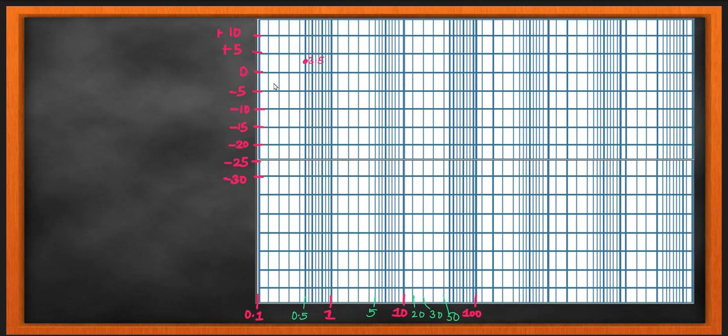So in your exams, you will be given logarithmic graph sheets in this manner. And in my y-axis, I have drawn the magnitude dB values, and then I'm starting to plot. So I have my 4 values, right? They are 3.5, minus 16.5, minus 16.5, and at the next corner frequency, minus 28.5.